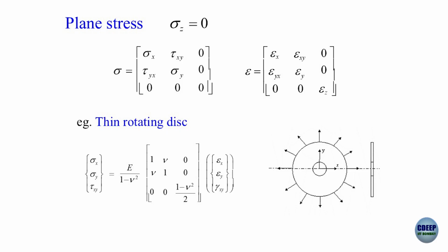So, now we have two levels. One is that I have to model xy to zeta eta, coordinates itself I am doing a transformation, and then I am doing the field variables modeling. So, coordinate modeling, geometry modeling, and then field variable modeling. There are two aspects to the finite element modeling when we come to 2 dimensions, 3 dimensions.